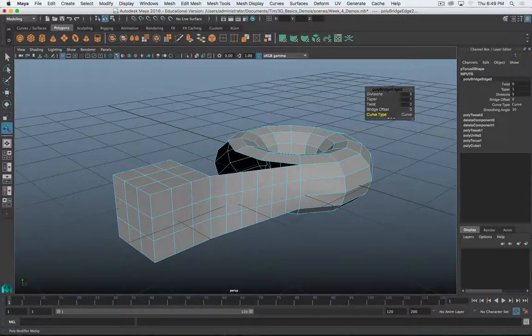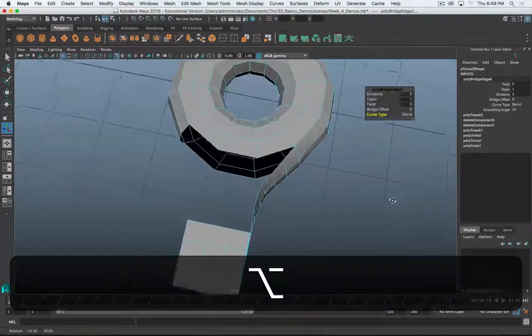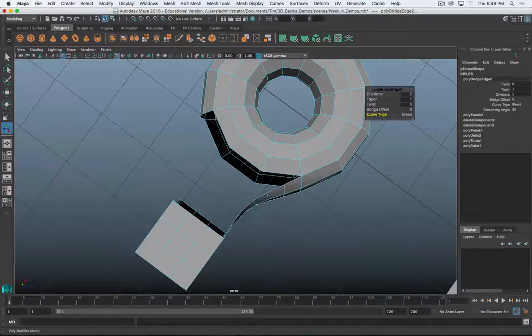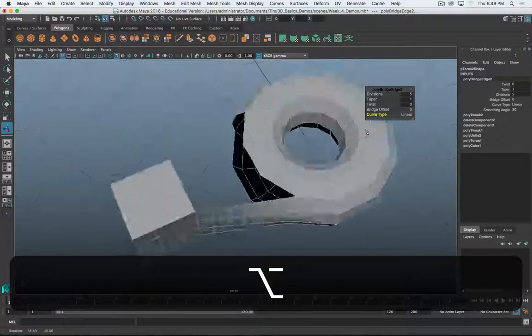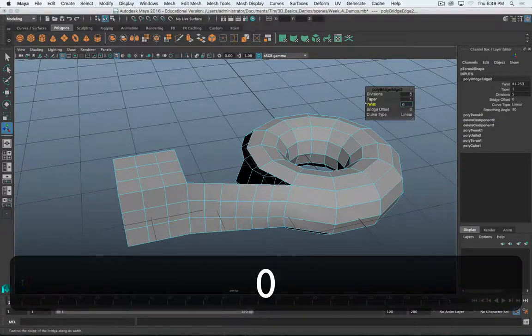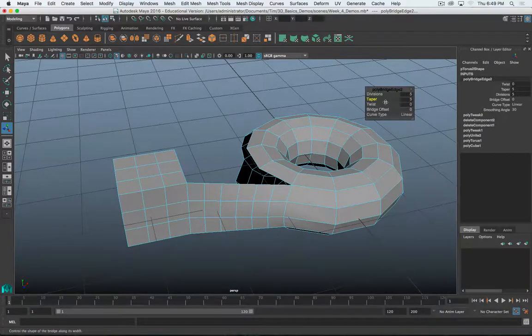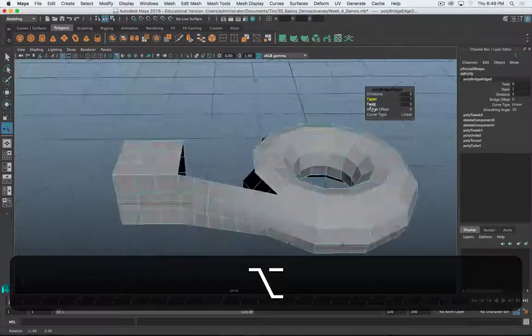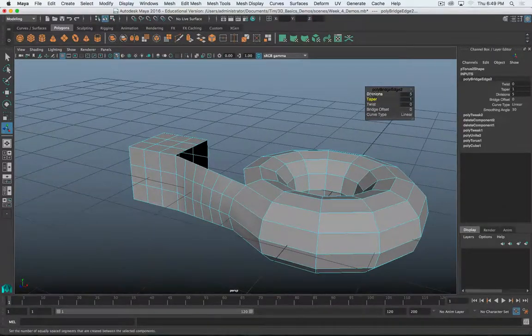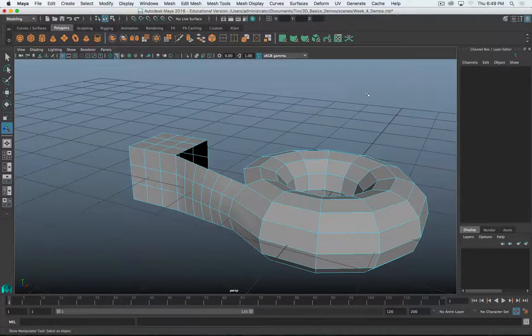And you can adjust the curve type if you want it to have a little bit of a bend to it. Curve, bend, or linear. You can see kind of the differences here. Bend is interesting. You can set twist, which isn't really doing much here, so I'll leave that at 0. I never really used twist or taper for this. I'm sure there are great reasons to use it. It hasn't really come up in my modeling needs.